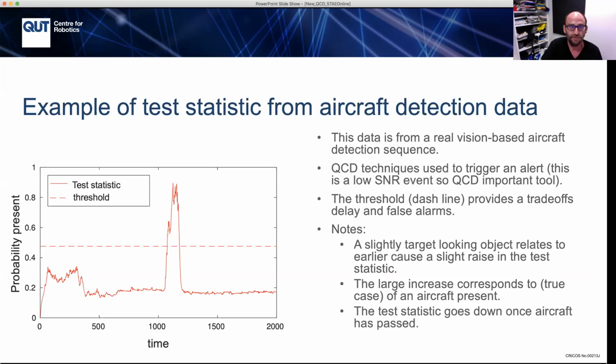I guess it's interesting that we got to fly two aircraft at each other in near collision course geometry. This point here corresponds to a cloud artifact that looks something like an aircraft. It started to confuse the detector, but not enough that it declares an alert. And so this is basically the sort of pictures I've been looking at for 10 years, trying to make the aircraft detection part higher and reduce these things here so that we get better detection performance in terms of the trade-off between detection range and false alarm.